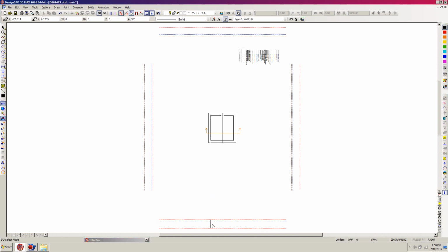Now what I want to do is create additional lines. I want to just create an inside wall line. I have the outside one established already, and then I want to deal with the wall lines for the rear wall, which is on the right hand side at this point. So I'm going to select this outside wall line, and I'm going to use the parallel command, which is the equals key. So you just hit it.